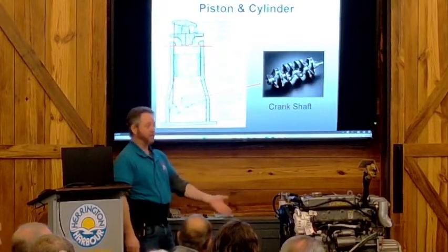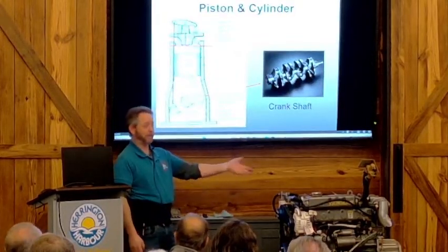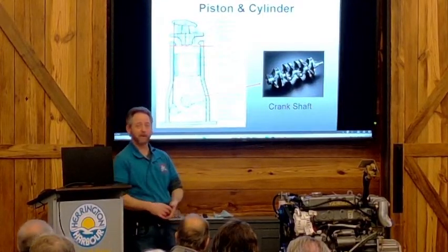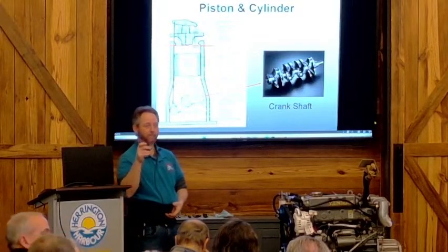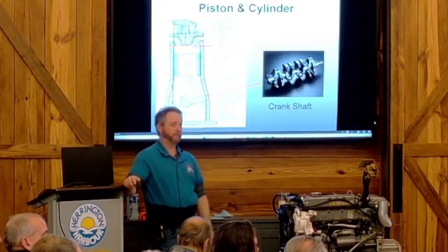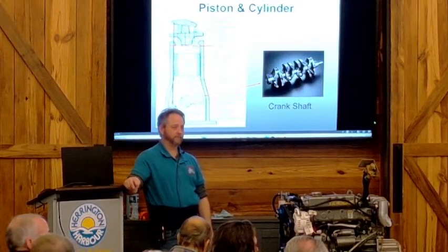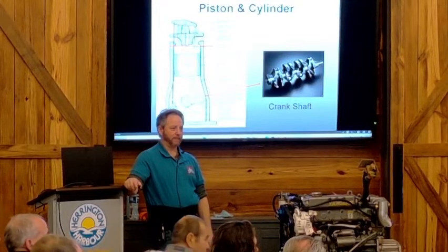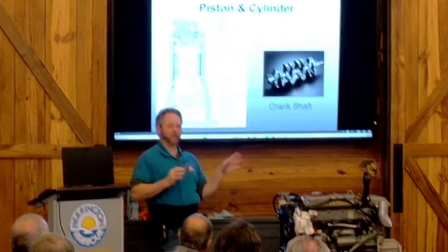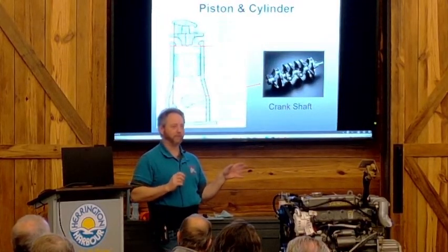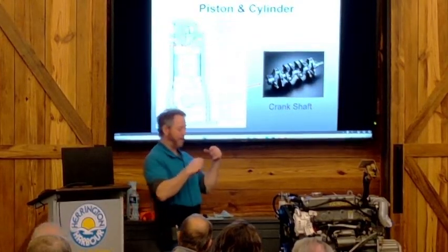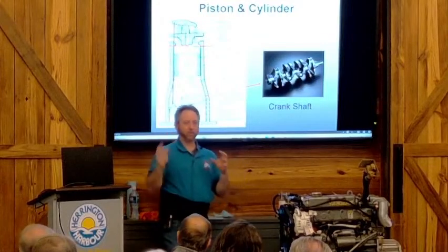And so an oil change for it is probably going to be $100 between oil and the filter. And you typically got more displacement on a diesel per given horsepower than you have on a gasoline engine. It could be, because it turns a lot slower. So, horsepower is just a funny word that they typically aren't using too much in the marine world anymore, because horsepower is just a combination of RPMs, revolutions per minute, and torque.